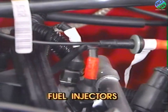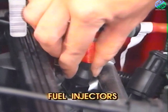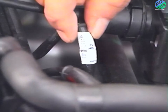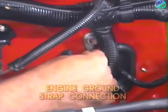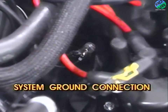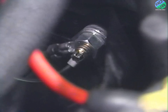And make sure that the fuel injector wire harness connectors are connected to the fuel injectors in the correct order. Each harness connector is tagged with the number of its corresponding injector at the factory. Also be sure to check items which are not inputs or outputs, such as the engine ground strap connection and the system ground connection located behind the dipstick. In each case, the connection must be tight and free of corrosion.